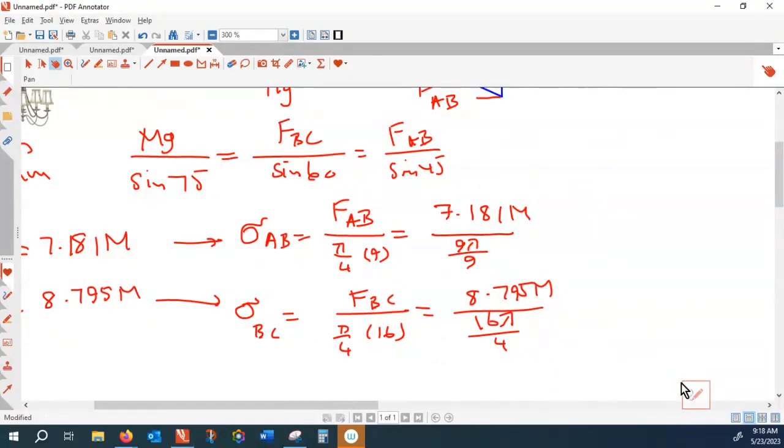And if I set this one equal to, I keep the 9.8 and this one in kilogram, that is Newton. Everything else is in millimeters, so that is megapascal. Megapascal, that if I set that equal to 150 megapascal, each one of these gives me a mass.